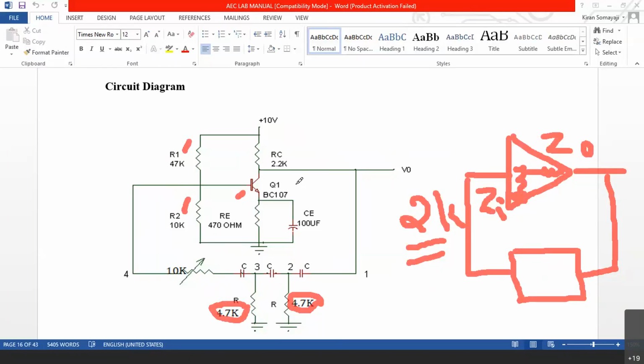Each resistor here has got 5% tolerance, and transistor to transistor, beta is different. Even though we are going for a voltage divider bias, where we can say that beta can be ignored, still for the impedance calculation we have R1 parallel with R2 parallel with beta into small re. Now R1 and R2 will have their own tolerances of plus or minus 5%, and the transistor will have a beta which differs from transistor to transistor.